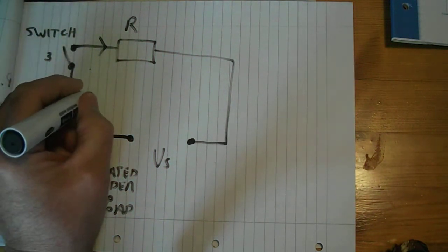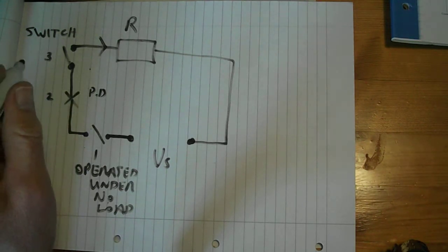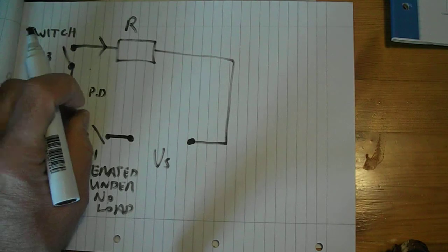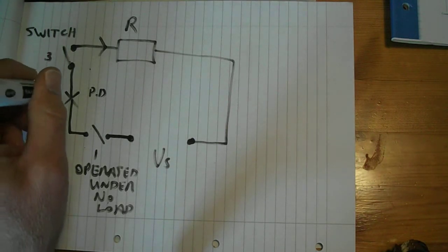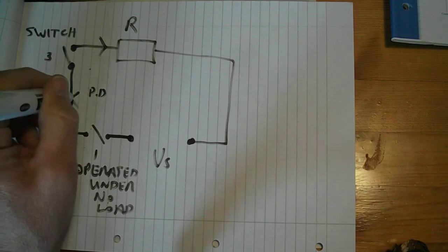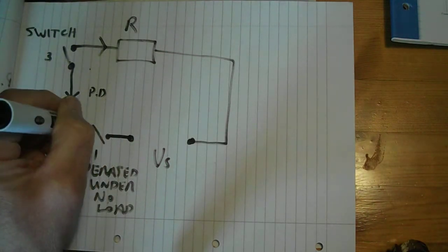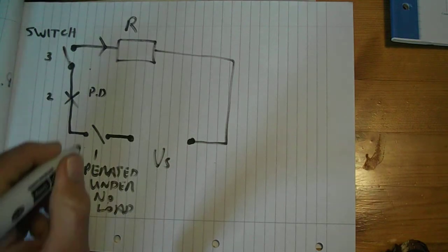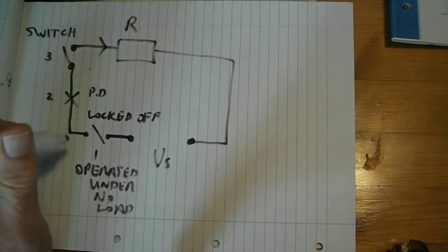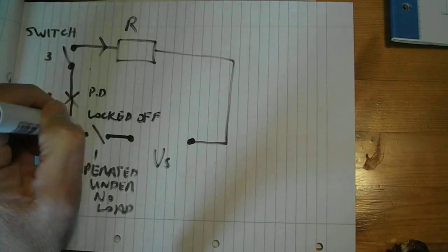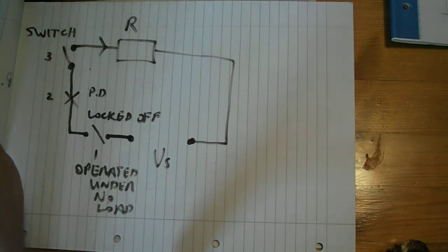And this is our protective device. It's a circuit breaker. Now, a circuit breaker is an automatic type of switch, which if too much current goes through it, it automatically operates like a circuit breaker does in your household consumer unit. But you can see here that if you wanted to work on the protective device, or you wanted to work on the switch as a fitter, then you would need to isolate the supply using this switch here. And this is very often what we call locked off. Literally with usually a couple of padlocks which keep it locked off for safety reasons when you're working on the rest of this circuit. Alright.